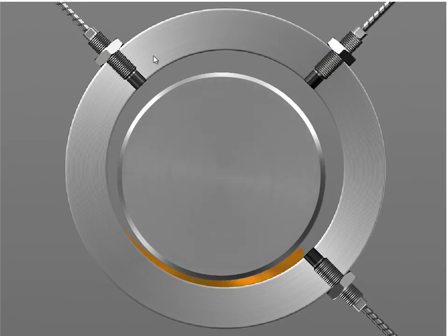These two probes are mounted 90 degrees apart, and we kind of triangulate the motion of the center of the shaft. I'll explain that a bit more in a second. The third probe here is not in the same plane as these ones. This one might be at the end of the rotor or somewhere where there's a key or keyway, and it measures that displacement, and that gives us our once per revolution information.